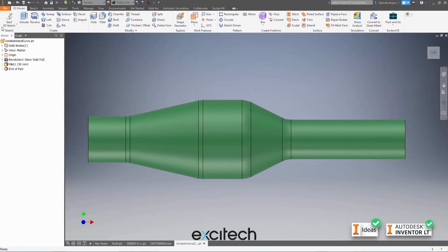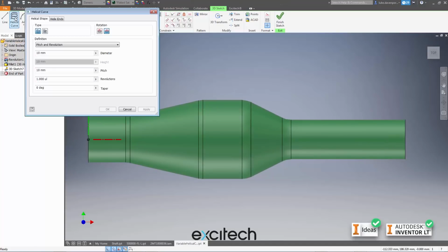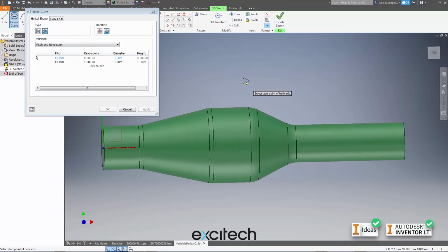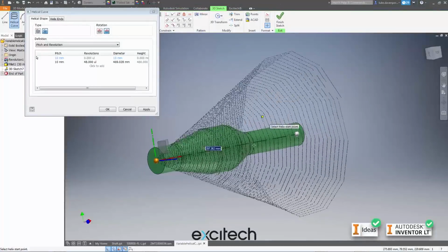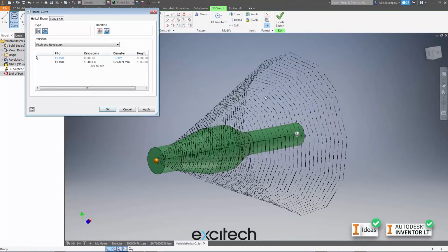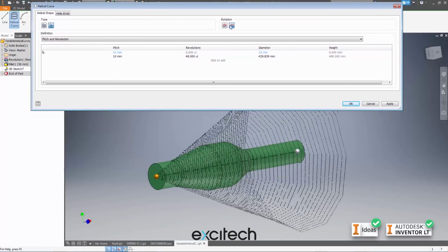So we start the 3D sketch command, and we use the helical curve tool here. This one's new, a variable helical curve, and here's the table that we can input the data in. But first let's position the start and end point of the helical curve. So the start point's here. Let's just put the end point on there for now, and you see we initially get just an option to put any old size in. Let's just drop this down here, and then we're starting to create our table. Let me just resize this to make it as easy as possible to see what's going on.